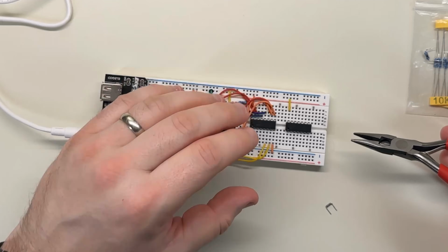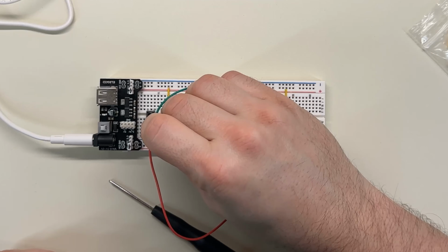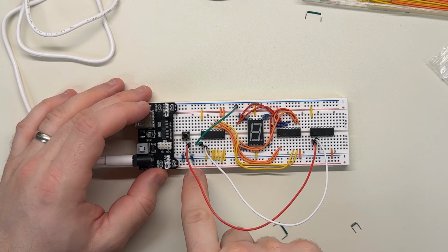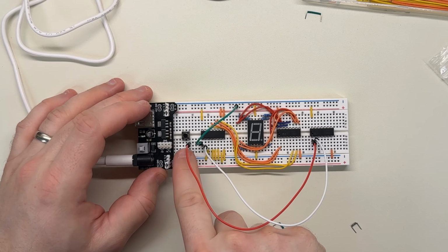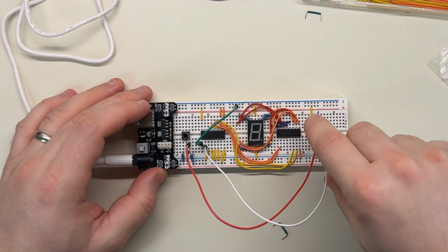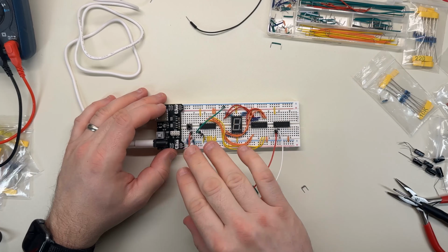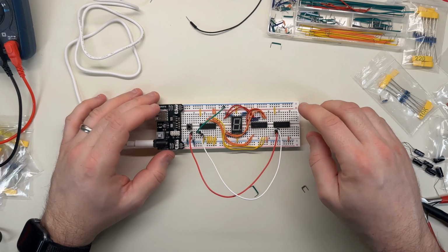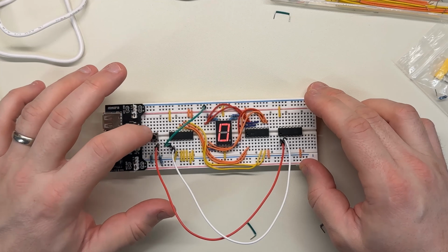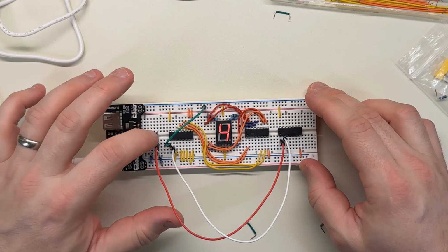Okay, so now I have it hooked up. The output of the switch, after this initial debounce circuit, this resistor capacitor, goes over to the chip, and then from the chip over to here, and I'm kind of running out of space. So without moving everything around, I just put it over here. So we'll see what happens. I'll turn this on, and look at that. It works quite a bit better.